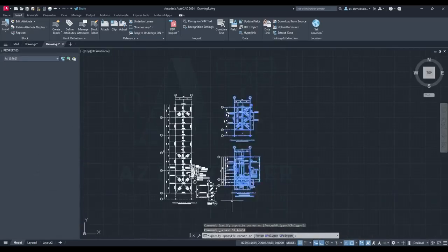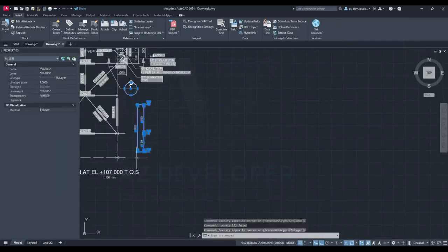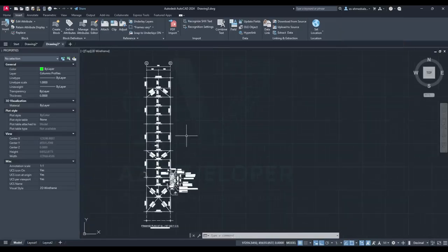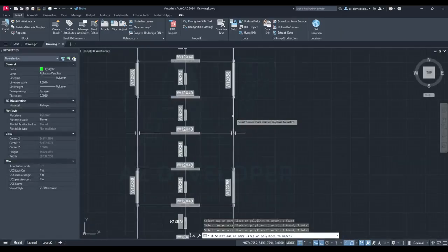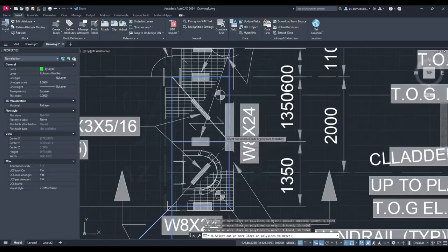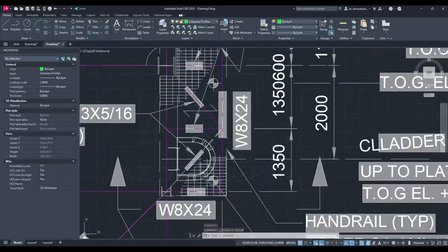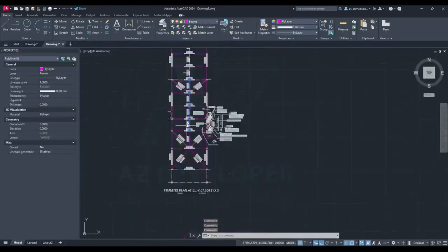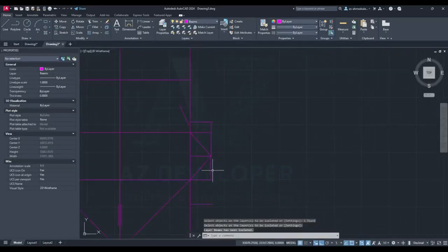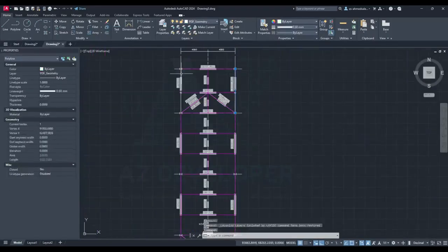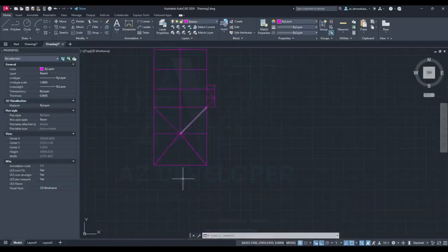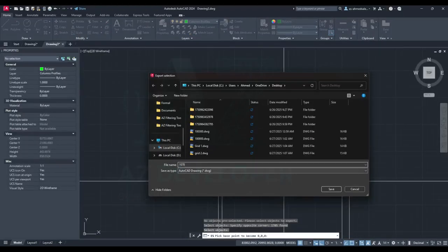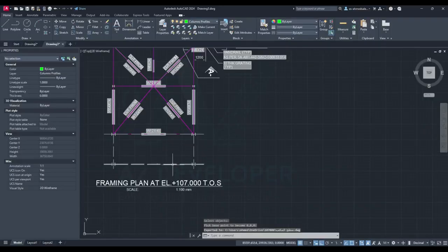We start by importing the PDF page into AutoCAD and cleaning it up a little. This step is optional, but it helps make things clearer and easier to work with. After that, we follow the same steps as before. Place beam lines on the beams layer, place column lines on the columns layer. Use whatever method works best to select the lines. Here, I'm using Select Similar based on length. Isolate the selection and make sure every frame line is selected. Now we save the plan, using the origin point just like we did earlier.